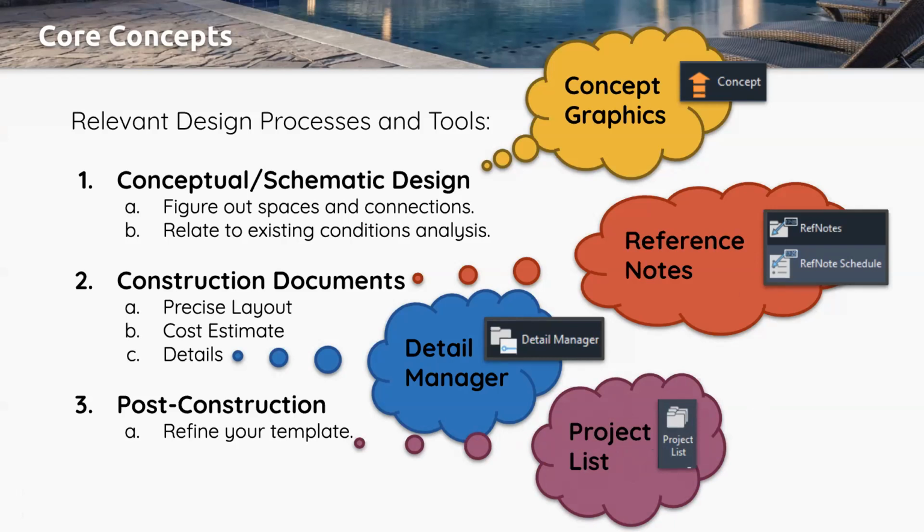You don't want to have to dig through 20 different projects, maybe file folders, sheets you've printed out, PDFs somewhere in your database, and try and remember how you worded the description of your paving area or your fence. Or try to remember what hatch did I use or what block did I use? Can I copy it from way over there? And what cost did I have it at? You want a spot to collect that information, to find it and pull it exactly when you need it. That's what templates do for you.